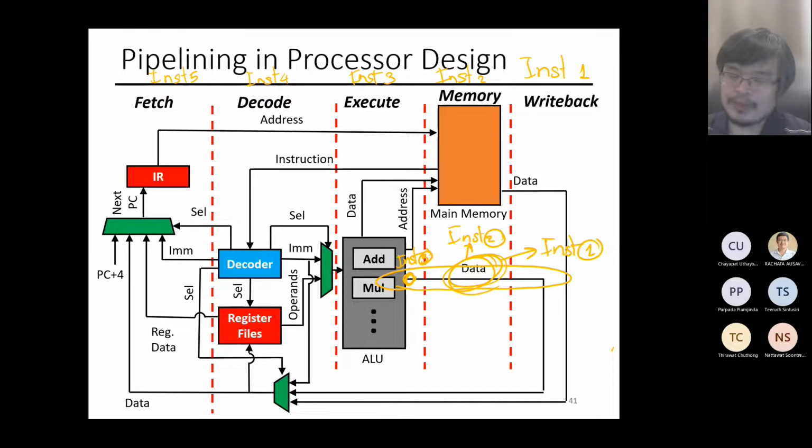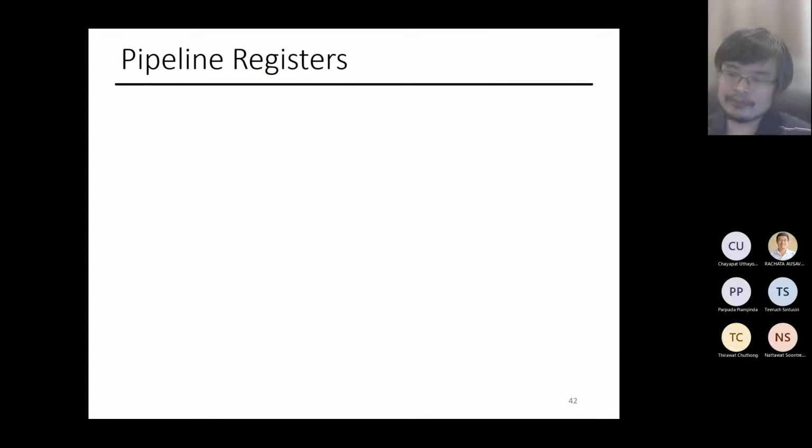Over here, between stage 1 and stage 2, from fetch, to decode, to execute, to memory, to write back. And we have a name for that. It's called a pipeline register. Whenever you talk about hardware design and you see the word register, you can think of it as a temporary variable in hardware that you can store a value in.